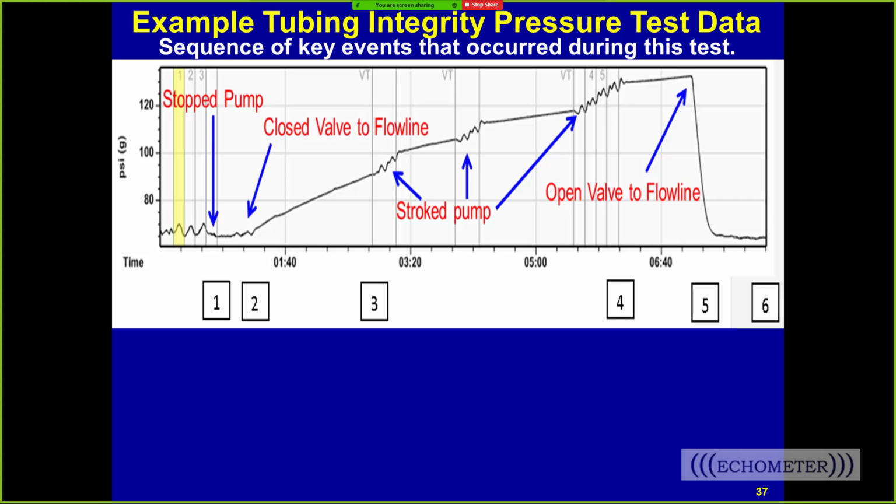If you attach your gas gun to the tubing and the well's pumping liquid up to the surface, then you won't really see anything other than noise because there's no place for the pressure wave to travel. So normally the well is going to be turned off, and you're going to shoot down the tubing with the well turned off.